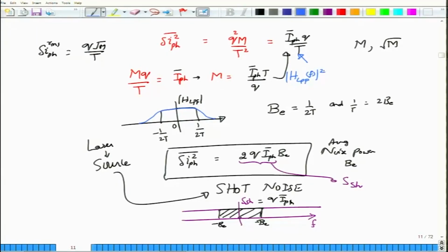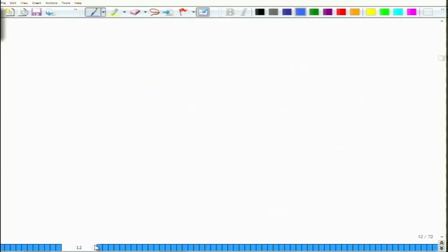So we assumed the shot noise to have this spectral density, which is perfectly fine. Now, instead of integrating over this rectangular bandwidth, you have to integrate over the actual non-ideal low pass filter, and when you integrate that, you will get the total shot noise contained in this bandwidth. Okay. So that is important, and there is another peculiarity that you must have noticed at this point.